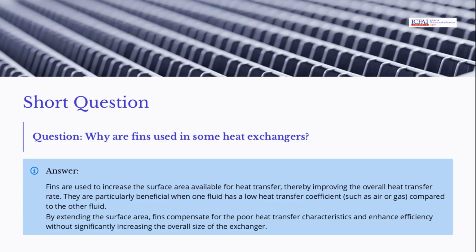Fins are used in heat exchangers to increase the surface area available for heat transfer, thereby improving the overall heat transfer rate. They are particularly beneficial when one fluid has a lower heat transfer coefficient compared to the other, such as air or gas. By extending the surface area, fins compensate for poor heat transfer characteristics and enhance efficiency without significantly increasing the overall size of the exchanger.